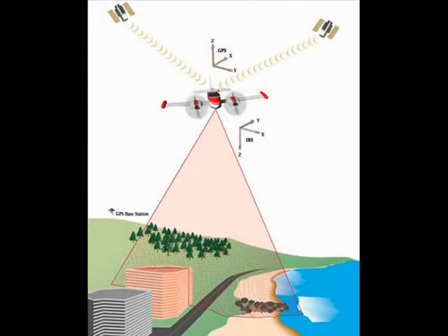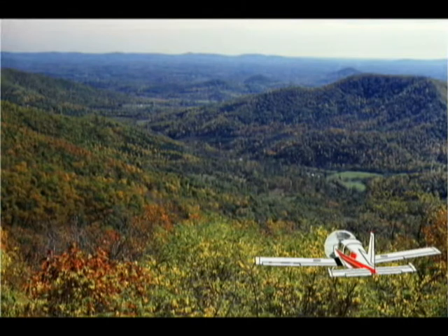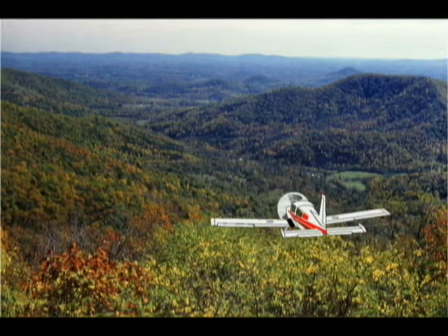This records all the data from all the systems and sensors and converts it into millions of XYZ coordinate points. All these components together, the laser, the IMU, the GPS, and the computer, are the basic units of the LIDAR system. From the LIDAR platform, the laser fires thousands of pulses to the ground every second.